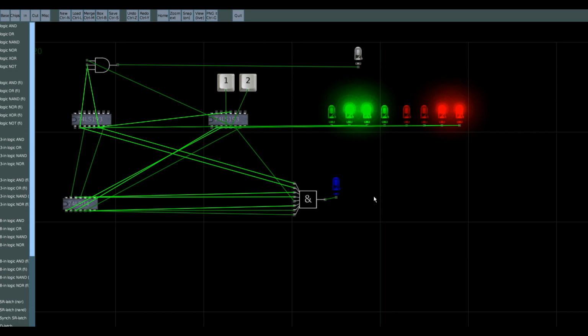But we're trying to get to them in 2 different ways. So if we look back to what we were just talking about, we have the need for 3 bits to be on for the number 100. So I've taken all 3 bits and I've passed them into this AND gate. And in the AND gate we need all 3 bits to be on, and this will make our light light. And this is basically our action. So if our action happens, we're happy.